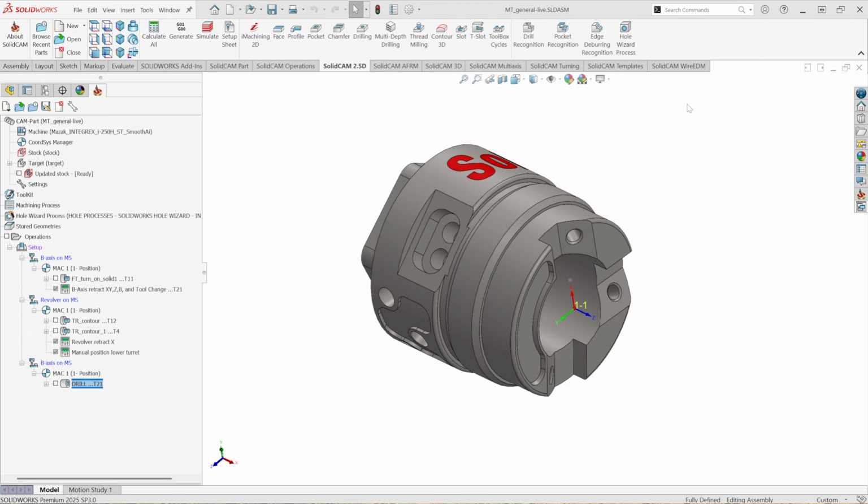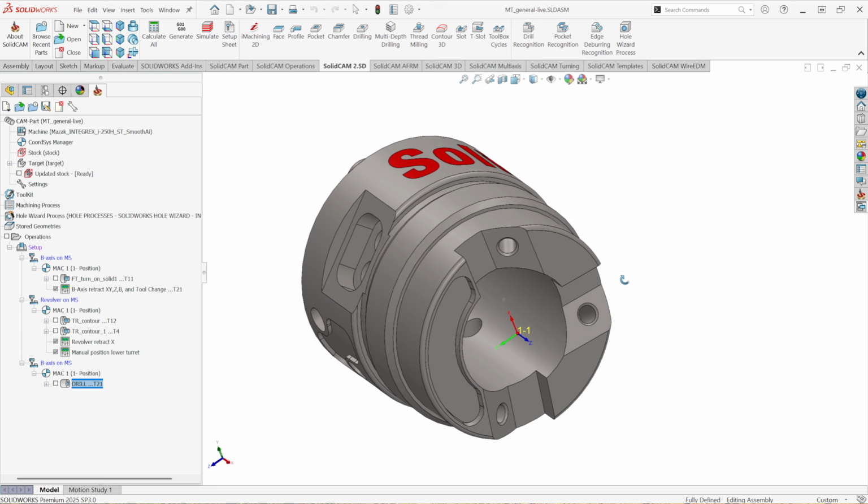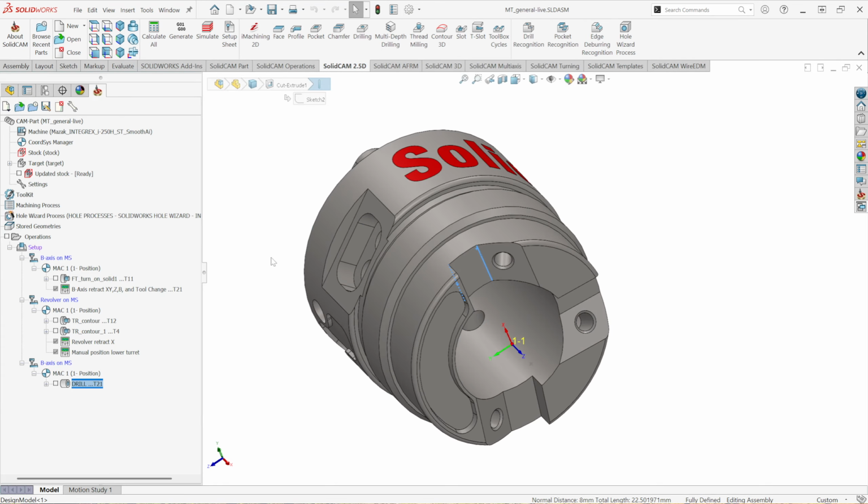In this video, we're going to start picking apart some of the milling features that we need to accomplish on this part. And for this first video, what we're going to do is focus on these faces. Doing a preliminary examination of the model itself, if I were to highlight this edge here and this edge here, I can see that this is at an 8 mm spacing. So here we can come in with a smaller tool and climb cut on both of the edges there. But in this case, we're going to grab an 8 mm tool to drive the center line of that groove to rough and finish that face.